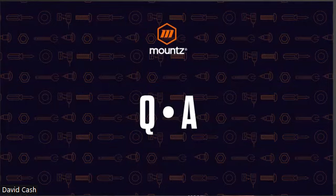All right, Dave. Next question we had was, what's the difference between a tool's accuracy and repeatability? So if we look at a bullseye target, and we have a tool that is repeating within a certain area very well, so all of the results for the readings are in a nice tight pattern, that would be repeatability.